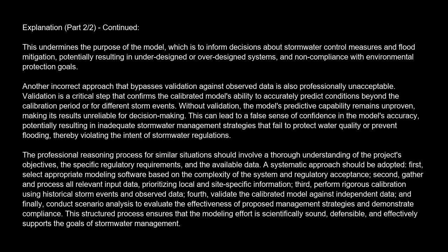Another incorrect approach that bypasses validation against observed data is also professionally unacceptable. Validation is a critical step that confirms the calibrated model's ability to accurately predict conditions beyond the calibration period or for different storm events. Without validation, the model's predictive capability remains unproven, making its results unreliable for decision-making. This can lead to a false sense of confidence in the model's accuracy, potentially resulting in inadequate stormwater management strategies